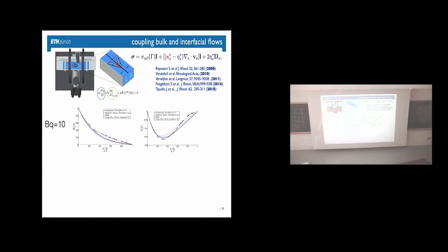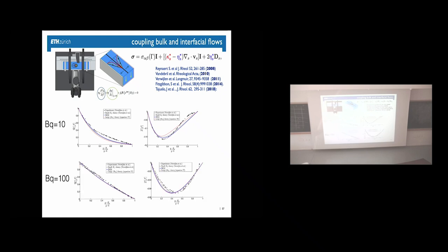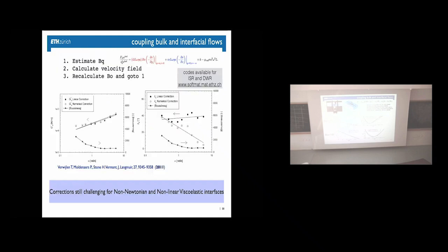And so you would measure an apparent viscoelasticity, where everything's Newtonian. Not good. It gets less, I mean, look at the axis. Here it's almost linear at the Boussinesq number of 100. The out-of-phase component becomes very, very small, and it gets better when you get to higher numbers. But it's a problem when you measure, right?